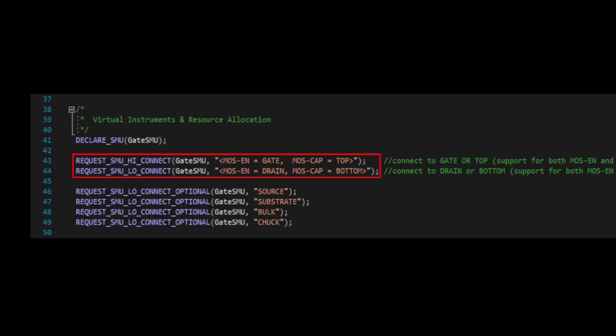Depending on which vendor's SMU you were using, this may seem confusing. Simply remember that any Keysight SMU always uses a global SMU low terminal called the ground unit. For Keysight instruments, that is what will be connected to SMU low. For Keithley SMUs, there are both high and low connections explicitly separate, so this will already be intuitive.